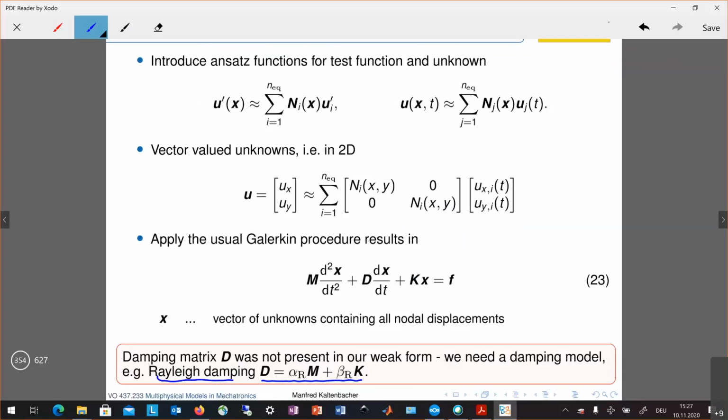That is a standard approach which does not really increase the computational burden of the problem you want to solve, and fits well in a lot of problems in practice. So it is just a question of how to get these two parameters alpha r and beta r, but there are some possibilities with experimental setups to get these parameters via the loss factor of the material.